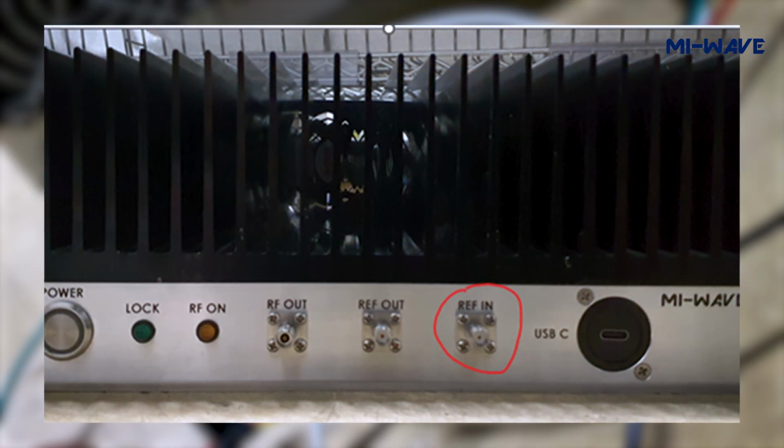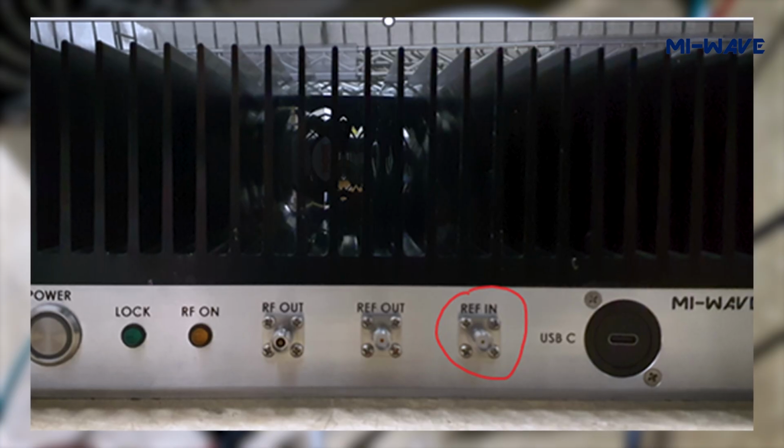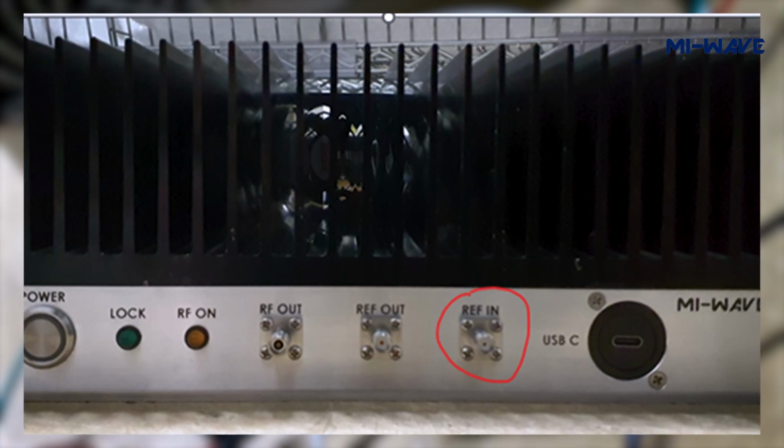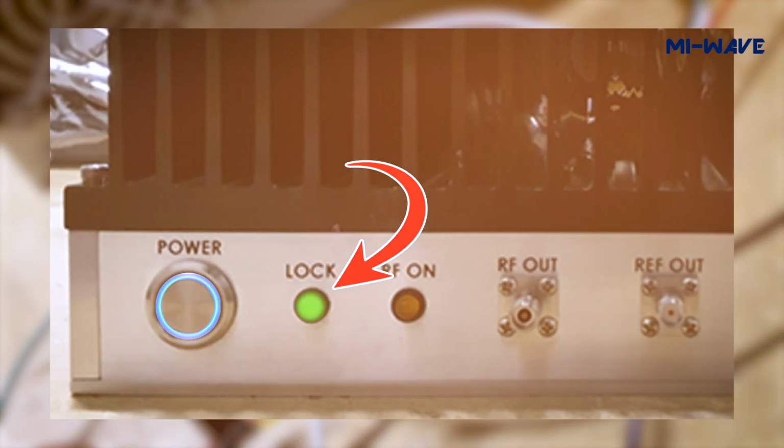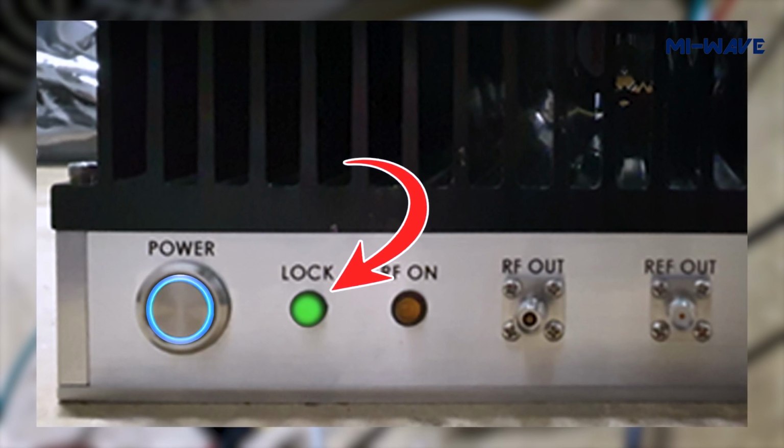The synthesizer can operate using an external frequency reference. Connect a stable 10 MHz external reference source to the ref in connector on the synthesizer. When the synthesizer successfully locks to the external frequency, the lock LED will illuminate, confirming a valid reference lock condition.